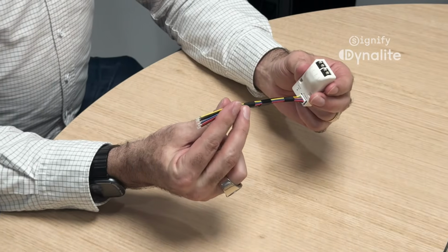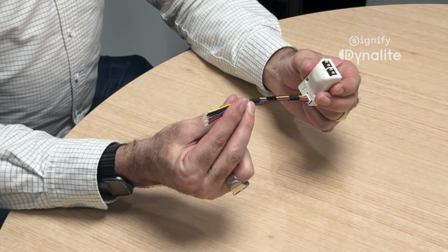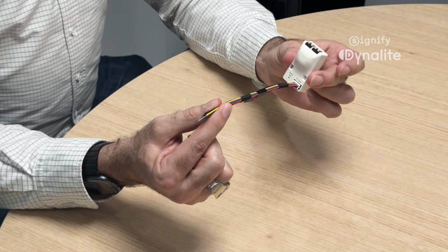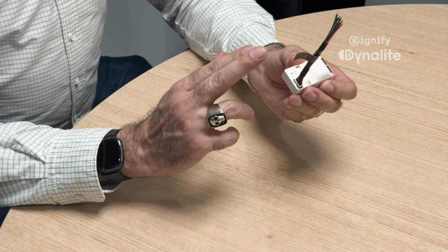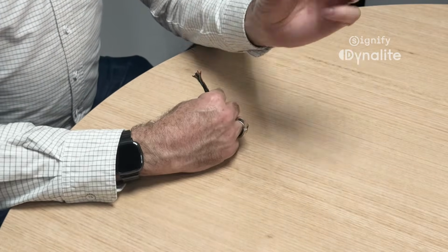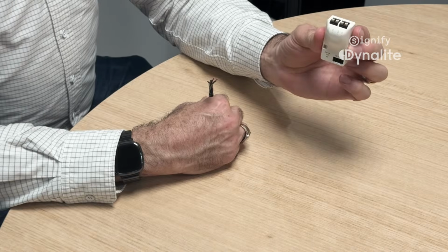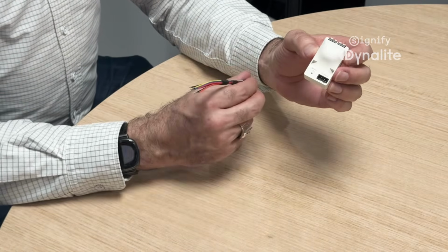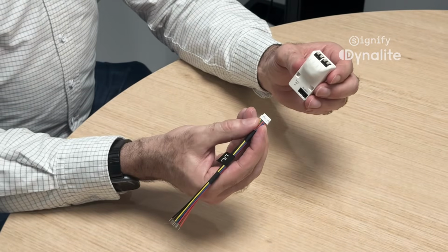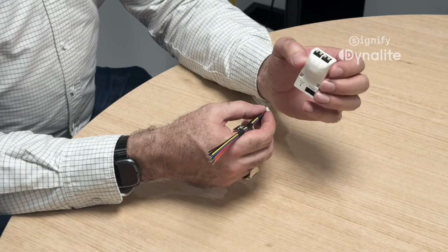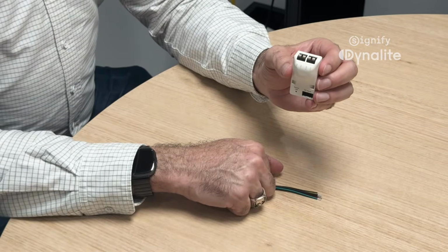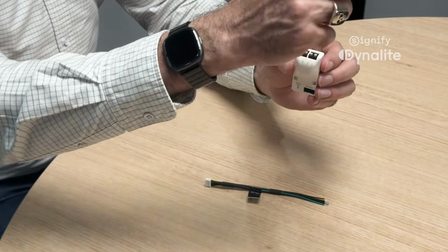So this is our DALI 2 dry contact input interface. It is 5 dry contact inputs available on the end of these fly leads. It is modeled after our Dynalite variant, so we have our plug lead here, which can be removed, and then this device can be fitted inside a wall box. We have some cable tie holes that will allow for this to be secured. Once that's done, then the fly lead clicks back in, allowing for a simple and quick install to be disassembled. We have our DALI terminals at the top, allowing for a loop in, loop out to the next device.